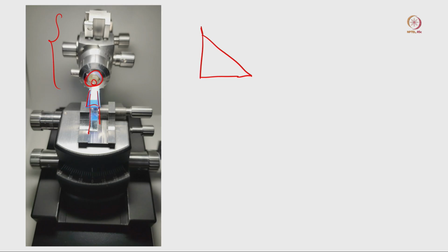This is the area where a small amount of water stores the different sections, and the glass knife helps us cut the sample properly. There are lots of other knobs which help us rotate, hold the sample properly, tilt or move it to a different position, and then we need the controller to move and cut the sample precisely.